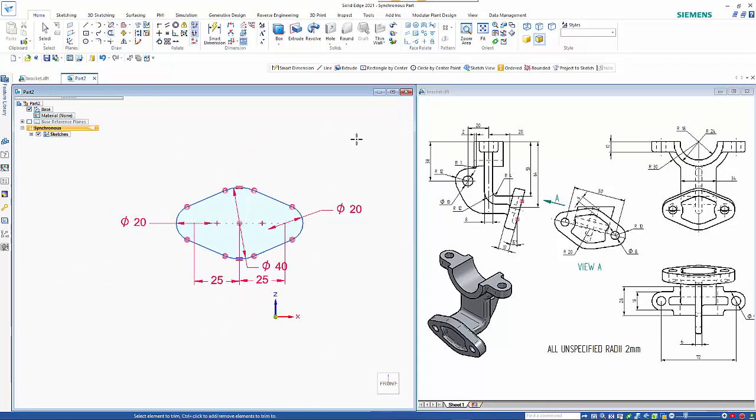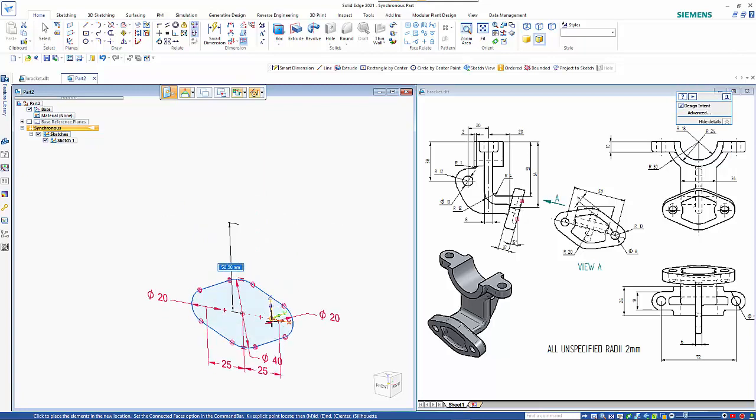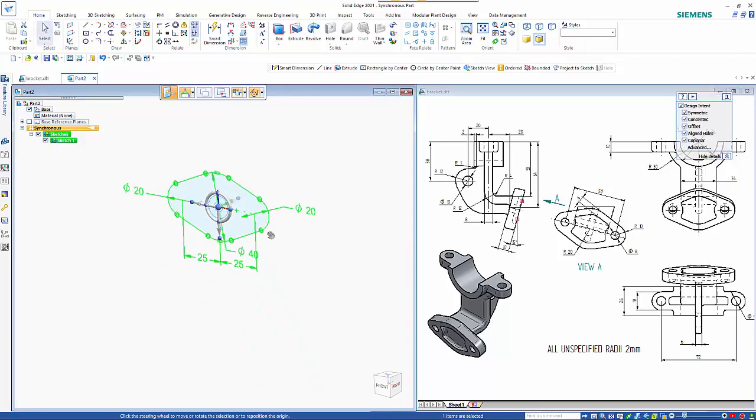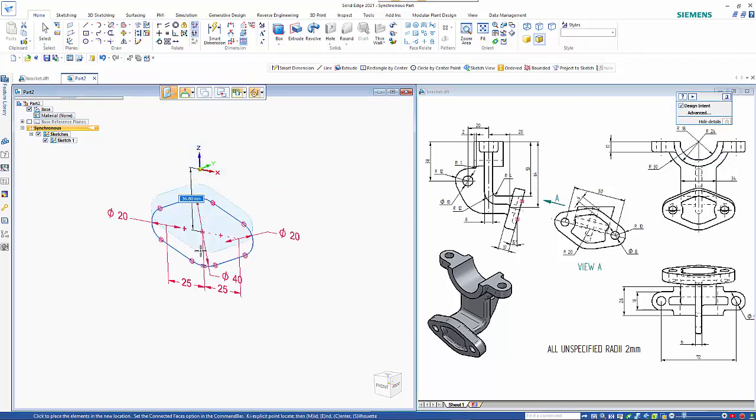So if I drop out of the locked plane, open out these sketches and select sketch 1, I can use my steering wheel to position it back over the center before I move it off, but I need this right in the center here. So if I just hover over the arc, it will do that for me. So I can then just drop it down. It's correct in the Y direction, so I just need to move it across in the other two. And then from here it needs to come down 64 and across 20. So we can drop that down.